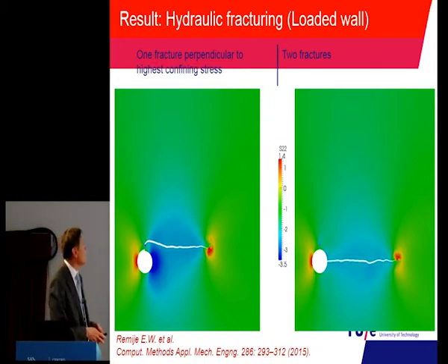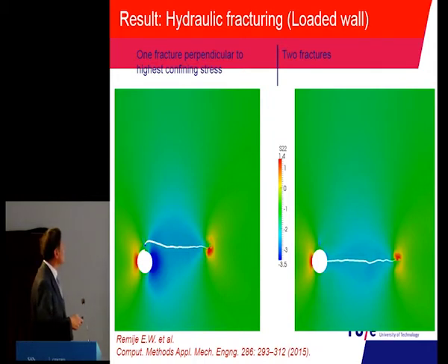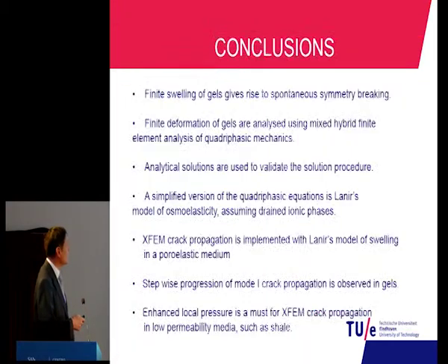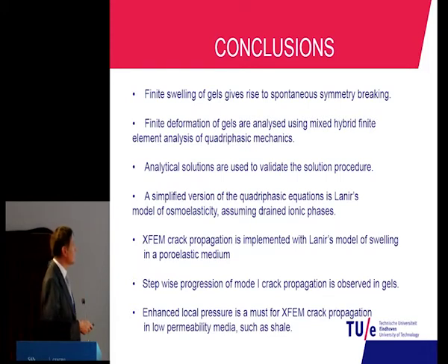So, in conclusion, finite swelling of gel gives rise to spontaneous symmetry breaking. Finite deformation of gels is analyzed using mixed hybrid finite element analysis, Raviart-Thomas type elements of quadriphasic mechanics. Analytical solutions are used to validate the solution procedure.